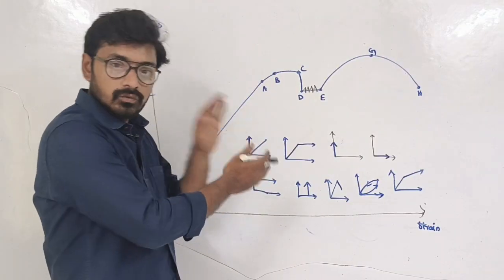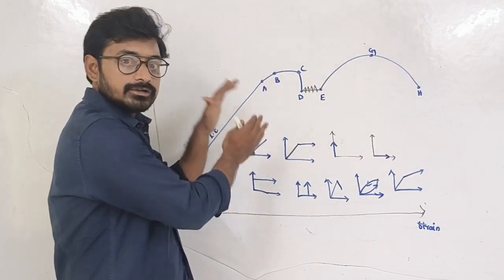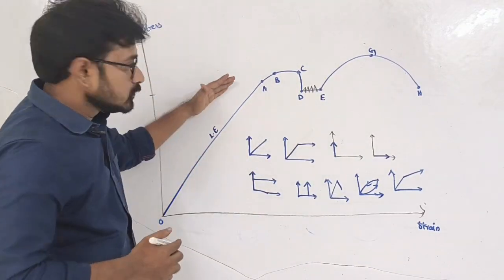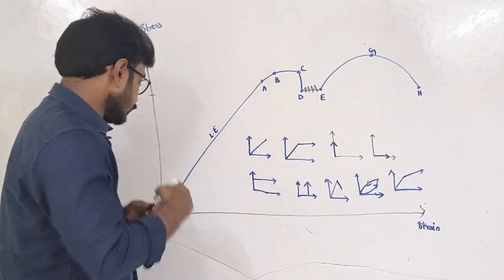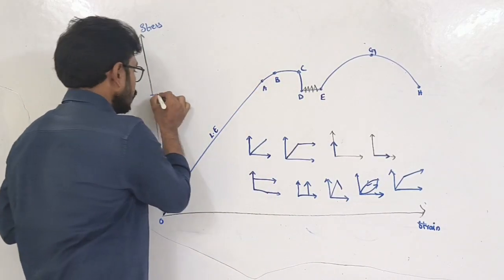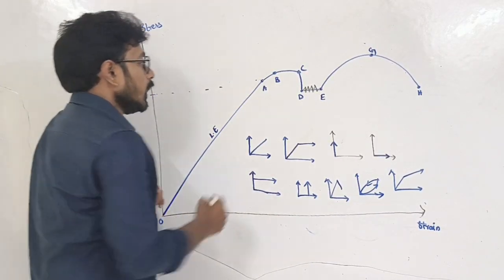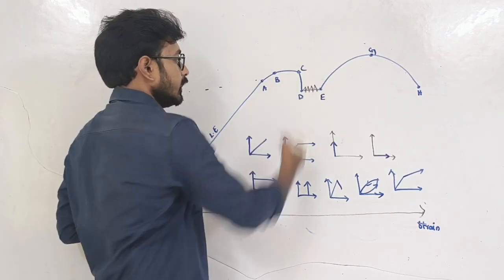As we all know, we have already come across the topic. So the stress strain curve will represent the material property. For the time being, let us revise a bit. In the last class, we discussed that here we will have our limit of proportionality. The value we are getting here is our Young's modulus, right? After that, we will have the elastic limit, and after that, the upper yield point.